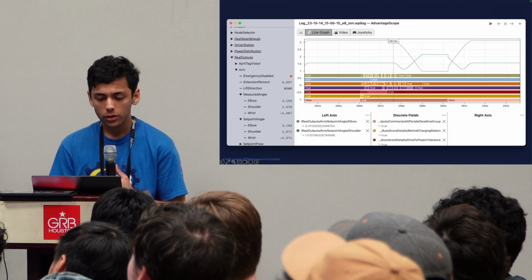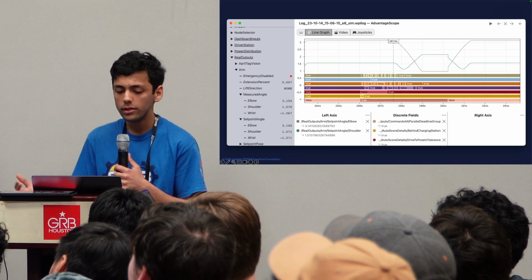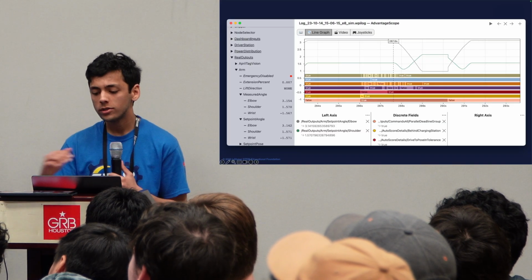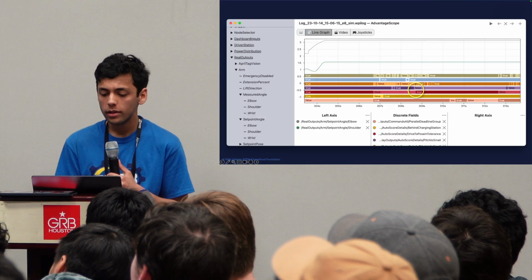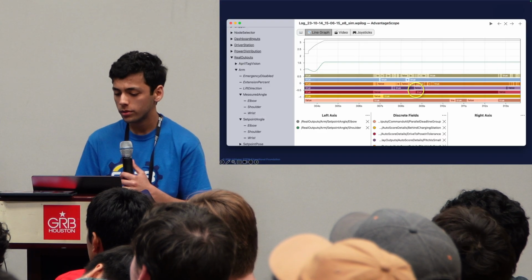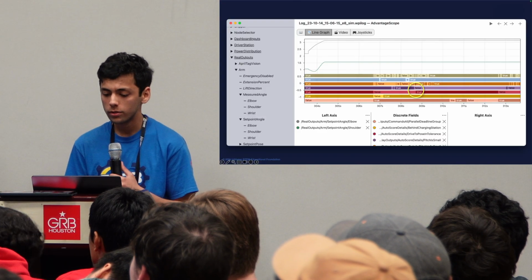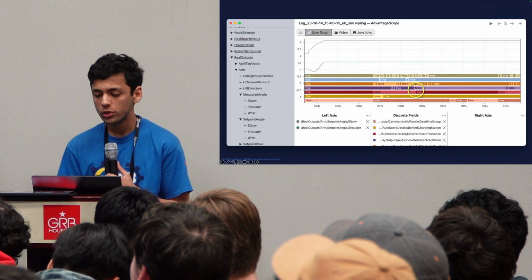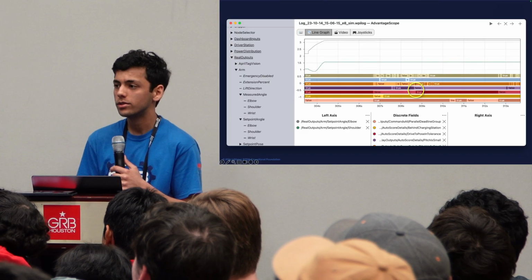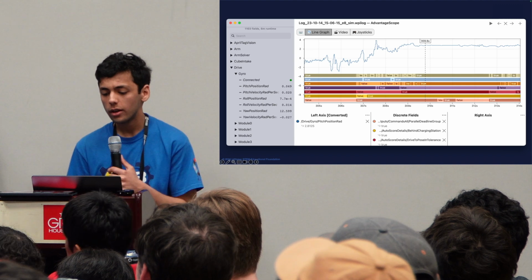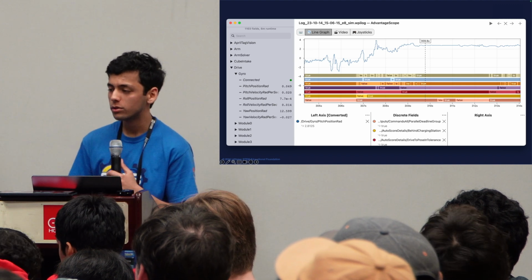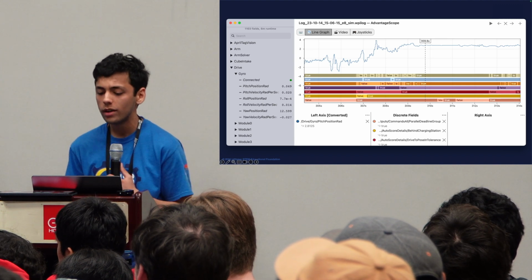And at the position of the cursor right now, we can see that this is the ideal state, this is how it's supposed to work, and all 6 conditions are true and the arm would move. This is when it fails. Notice right here, the red shows that the pose is in tolerance, the purple shows that the pitch is in tolerance. But just as we get close, the pitch changes too much, and it stays that way, so we can't extend our arm. If we check the pitch data, we see that our pitch settled at around 2.8 degrees, which is just 0.3 away from our 2.5 tolerance.